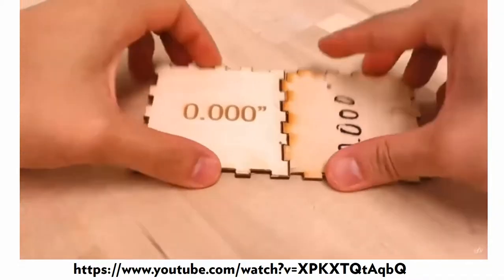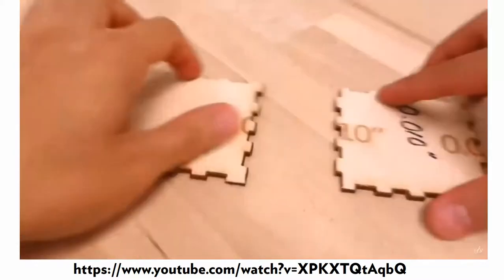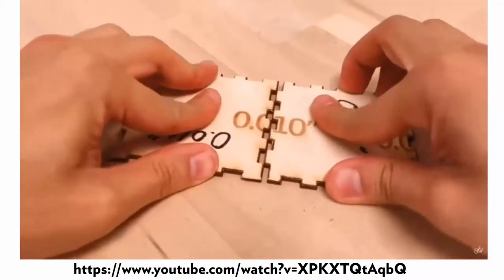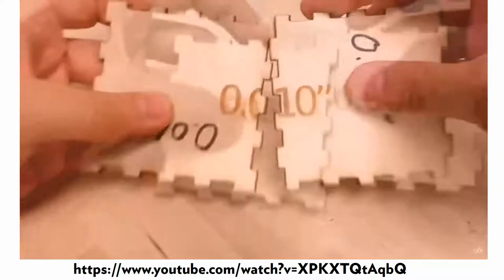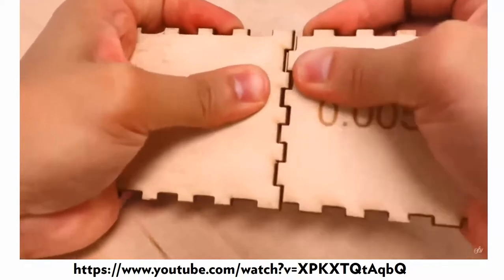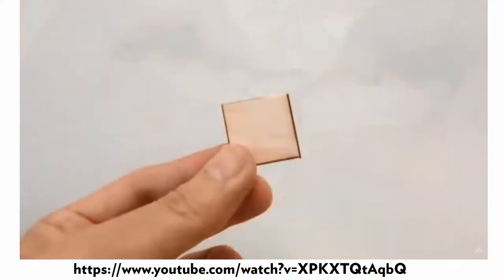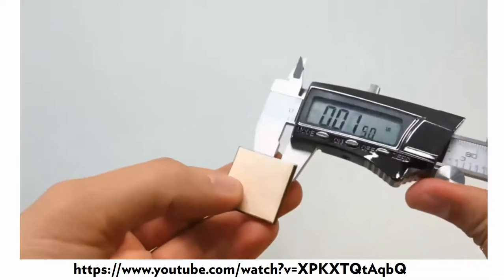When we set the kerf at 0, and this is assuming no kerf, the box is going to be way too loose. When you make the kerf too large, here we have it at 0.01, the parts are going to be too tight. For this material, which is 5mm plywood, 0.005 as the kerf is what's going to get our best results. So by understanding kerf, you can adjust your joints to be loose or tight.